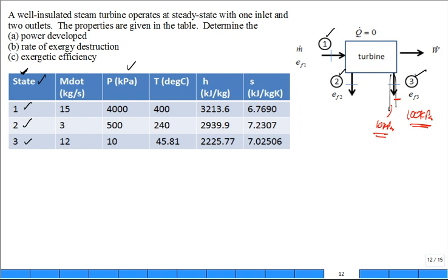All right? Try to wrap your head around that one. I try to beat it into students in Thermo 1, but we'll try it a little bit in Thermo 2 as well. But yes, it's a state of vacuum in that pipe. It's pure steam. They want pure water. They don't want air mixed in there. They work hard to get the air that may leak in there or began in there to get out of there. Engineers do. Okay? But you want pure steam in the pipe, and yes, it can be at that pressure.